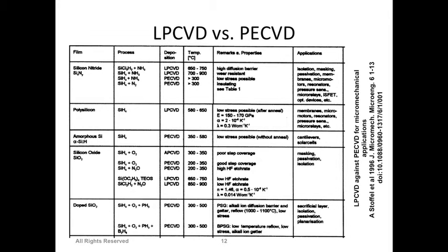You should be able to point out easily that SiH4, only one gas, cannot be used to make silicon dioxide because there is no oxygen source there. It's just SiH4. Most probably you can deposit silicon on the surface with that, or you bring oxygen from some other source. So that kind of understanding you should have, but you don't have to really memorize what formulas are used.